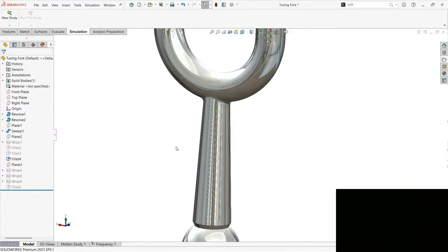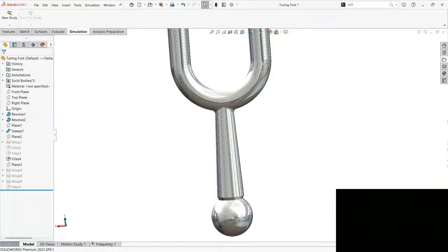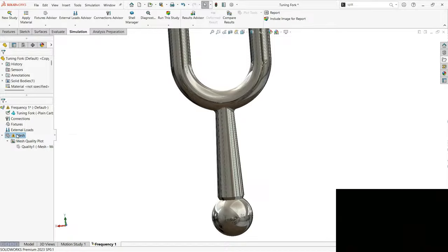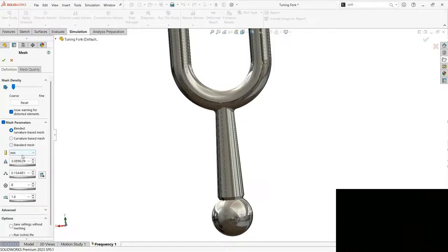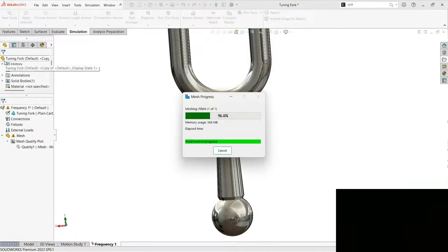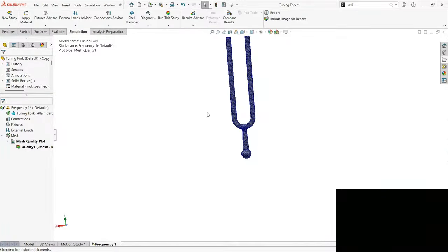These two are gone, so I think it should work. Now instead of a 3 mm mesh, we'll reduce the mesh size slightly to 2 mm, this time curvature based. I'd like to take the growth ratio 1.2, which is the standard. Green check. This looks fine.